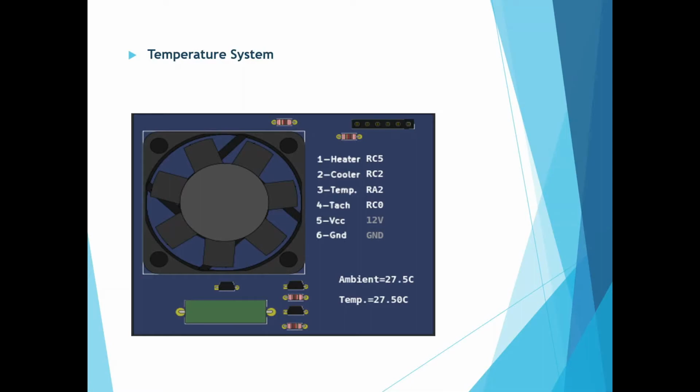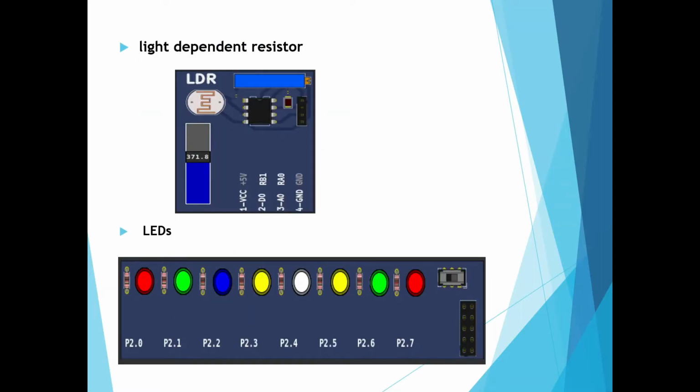Next, we look into the light-dependent resistor. A light-dependent resistor is also called a photoresistor or a cadmium sulfide cell. It is also called a photoconductor. It is basically a photocell that works on the principle of photoconductivity. The passive component is basically a resistor whose resistance value decreases when the intensity of light increases. The optoelectronic device is mostly used in light varying sensor circuits and light and dark activated switching circuits. Some of its applications include camera light meters, street lights, and outdoor clocks.